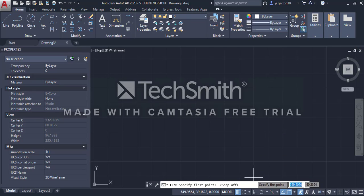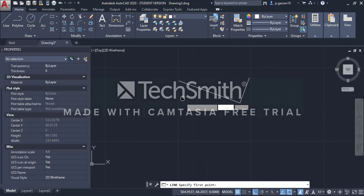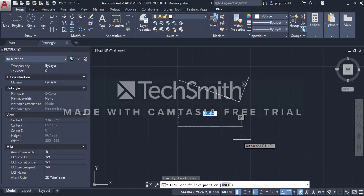The next option is called Ortho Mode. This Ortho Mode enables you to draw at 90 degrees. If you turn it off, you can draw at different angles. However, if you turn it on and then draw a line again, you will only draw at 90 degrees.